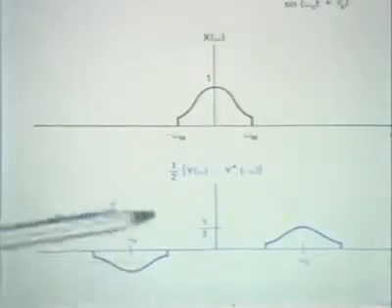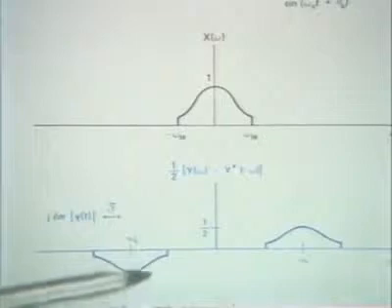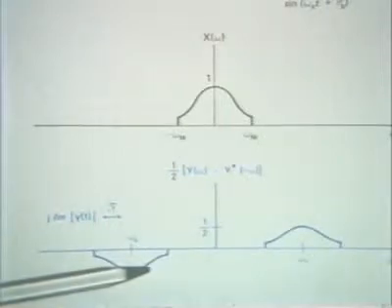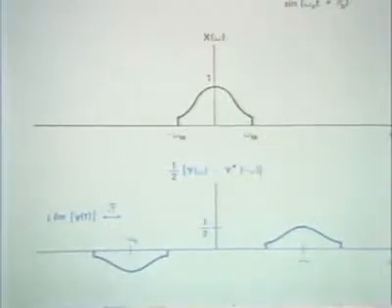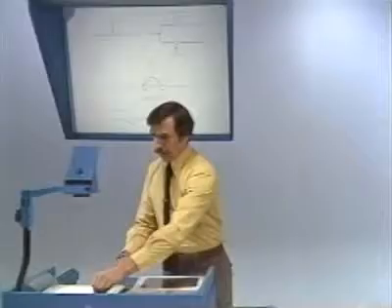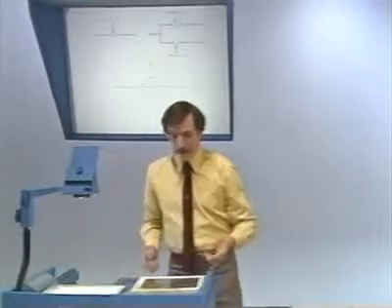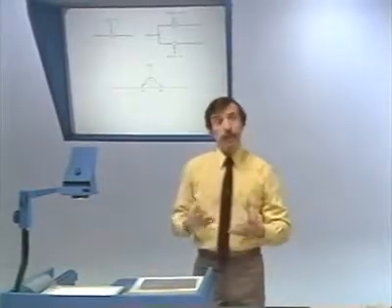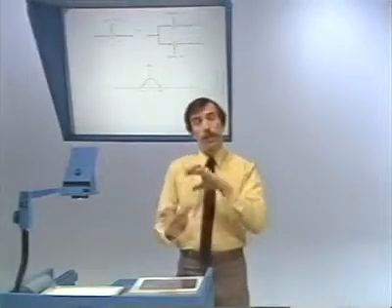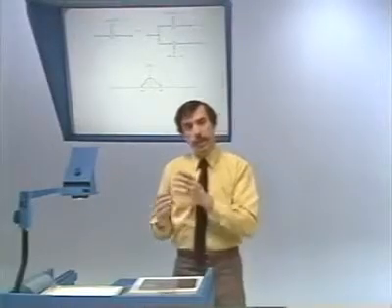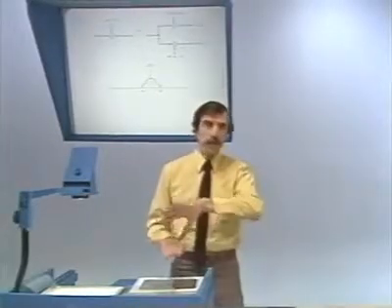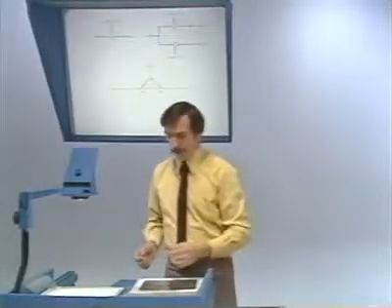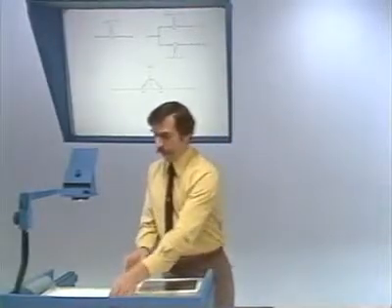And so in effect, when you add them, this portion of the spectrum will cancel out. So in effect, what we're doing is building the spectrum of the complex signal out of separate lines that represent the even and the odd parts.